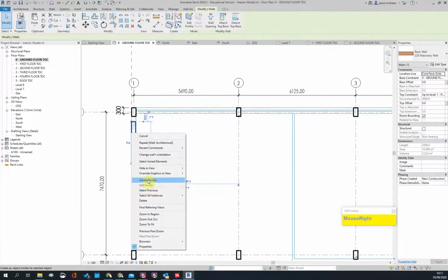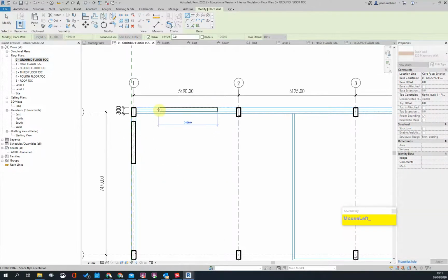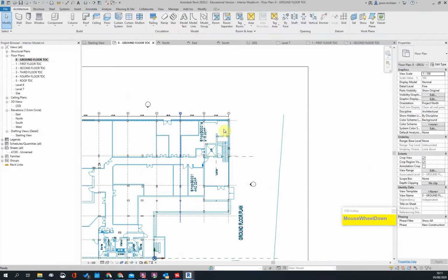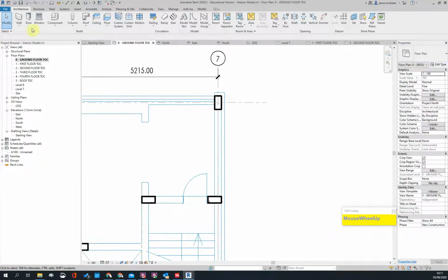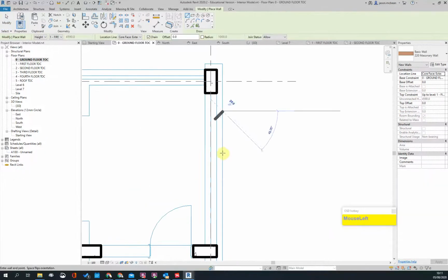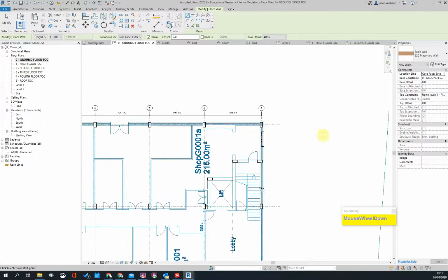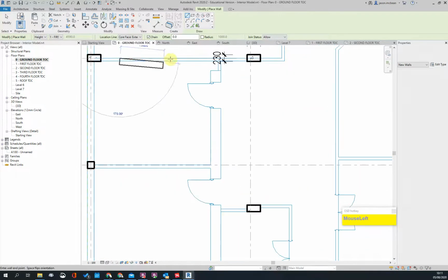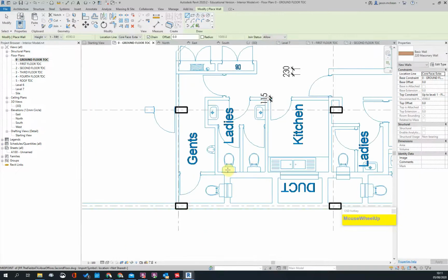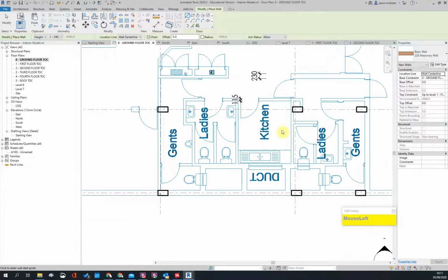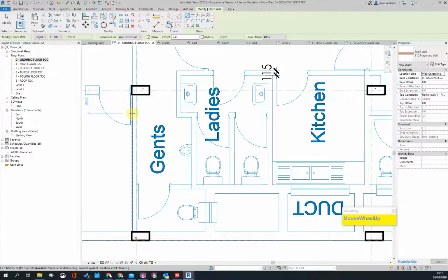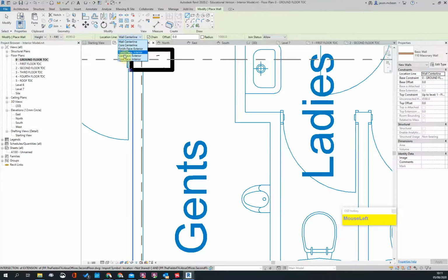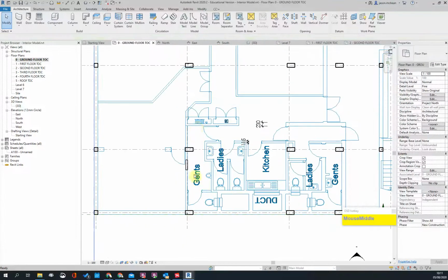I'm going to create similar. I'm going to put the wall over here, remember, core face exterior, and I've got another wall over here I need to establish, again core face exterior. So I need to make a wall type over there, and a wall type over there. I've got a stud wall that I need to establish as well. We can start using center lines, exterior lines for the time being, and I've got a 110 wall that I need to maybe establish over here somewhere. Again, keep the settings, core face exterior. You can use core center line or wall center line for this instance. Revit tries to find the center lines. Okay, so I need to make some adjustments.